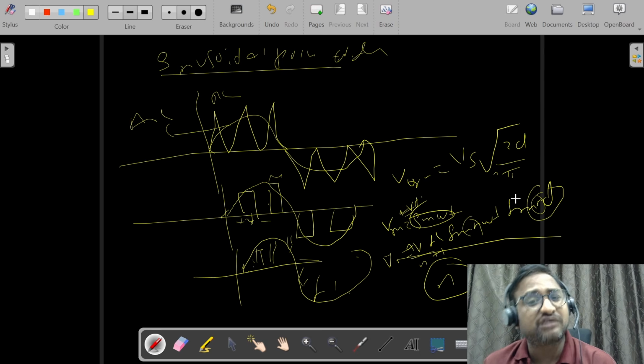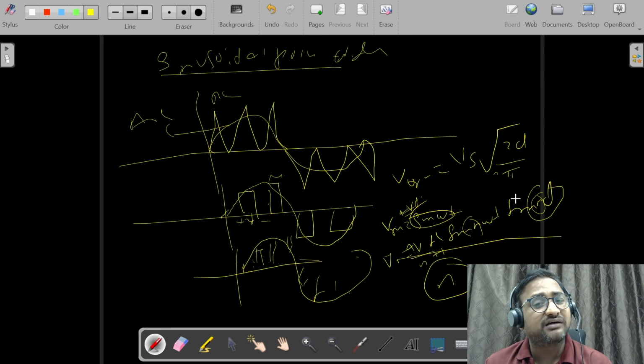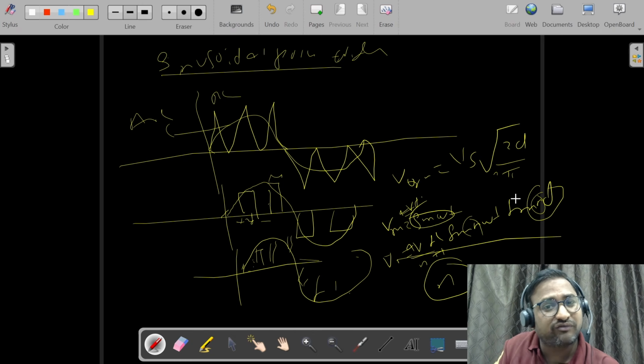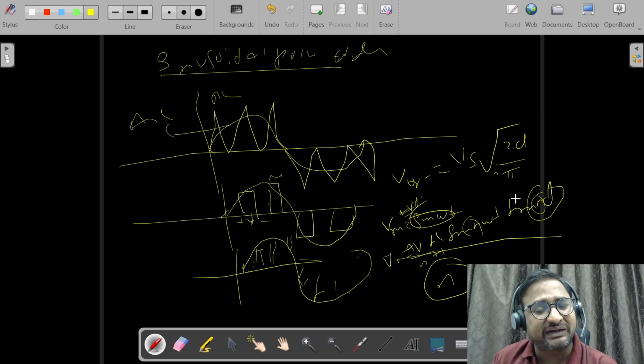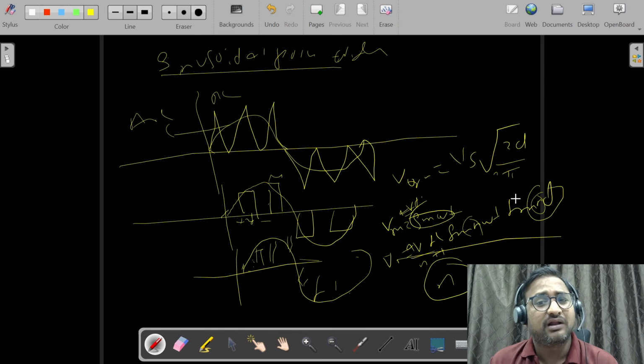And after the production of harmonics, how can we reduce them? I said, as the order of harmonic increases, amplitude decreases. For higher order harmonics, like for example the 20th, 50th, 15th, 17th, 18th, 19th harmonics, their amplitude is so small. For example, if the fundamental frequency amplitude is A, the 17th harmonic is A by 17, which is less than the fundamental, and that can be reduced by using a small filter like an RLC filter.